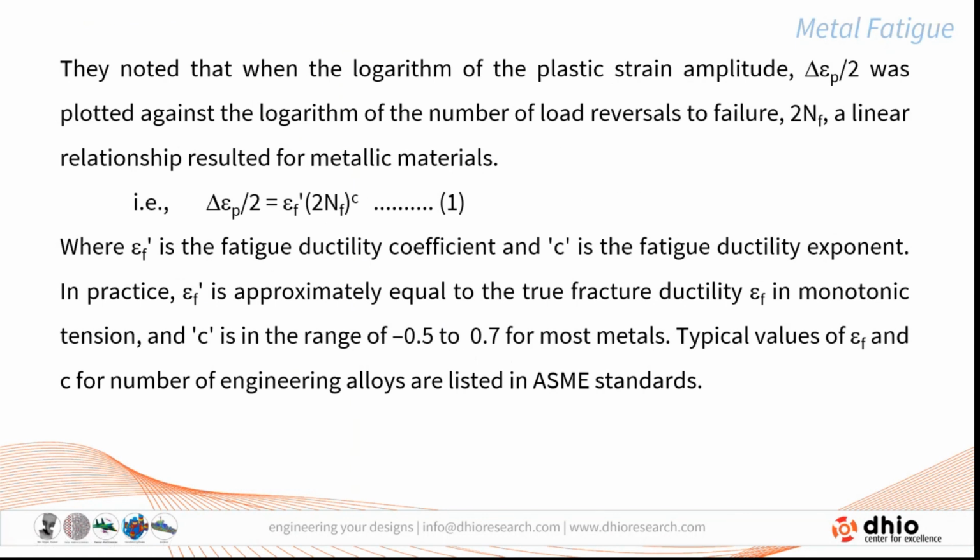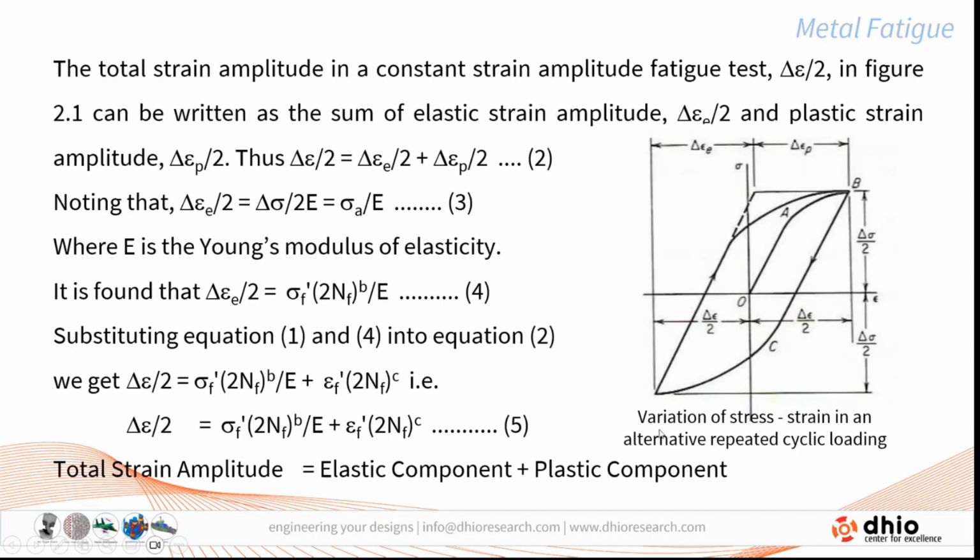And they noted that the logarithm of the plastic strain amplitude, plotted against the number of loading reversal cycles, relates the increment in the plastic strain to the number of cycles. Here you can see the variations of the stress distribution, and there will be some amount of stress or strain in the plastic zone and in the elastic zone. So the total strain induced is going to be partially elastic and partially plastic.